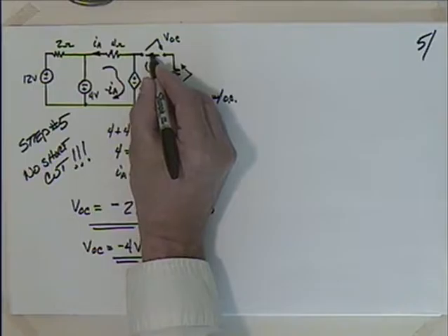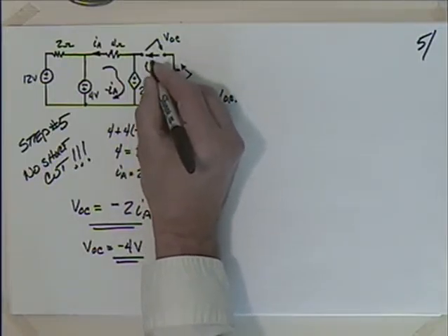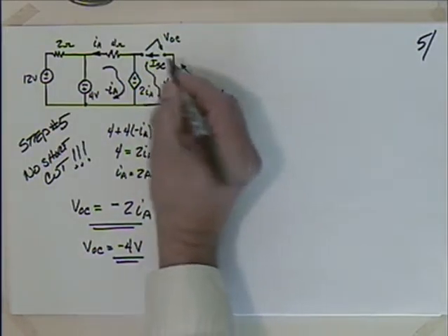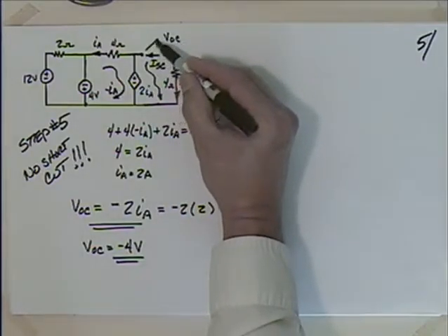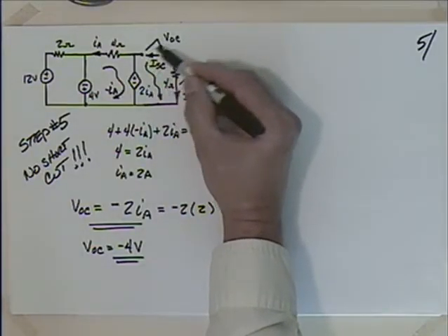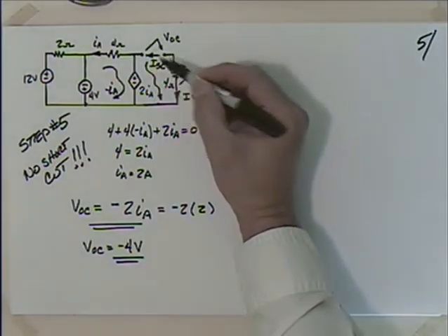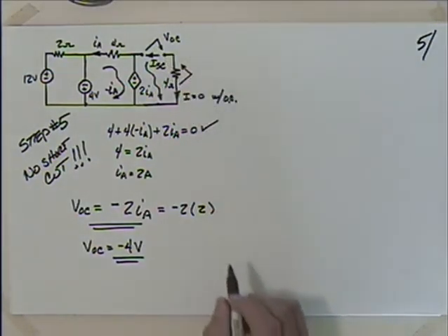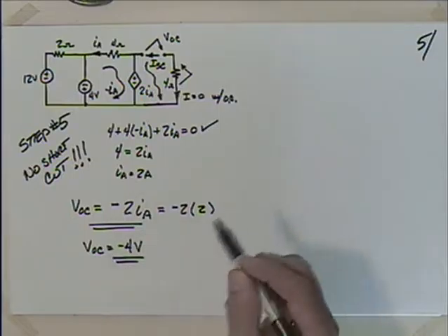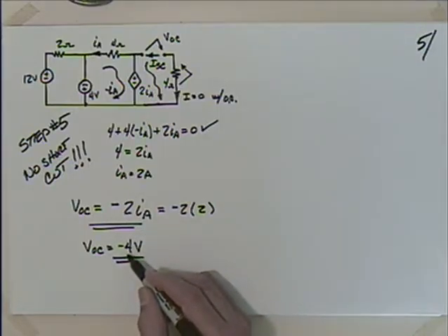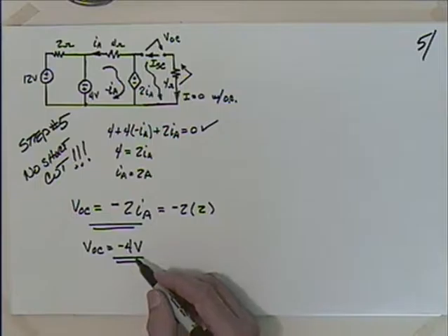So I'll put this current in here, and I say that's I short circuit. So if I'm committing to the voltage going from here to there, the current will have to be directed in the opposite direction of that. Okay. And the other thing for us to get a positive resistance is we're going to expect, and we'd better get, the short circuit being a negative number. Well, let's see if we can go through that then.